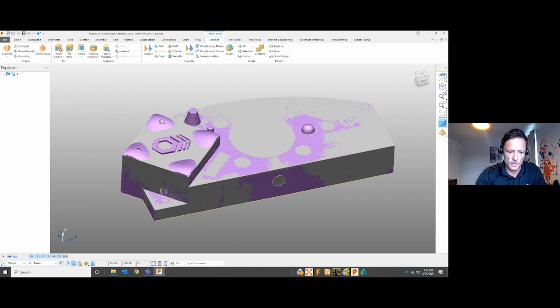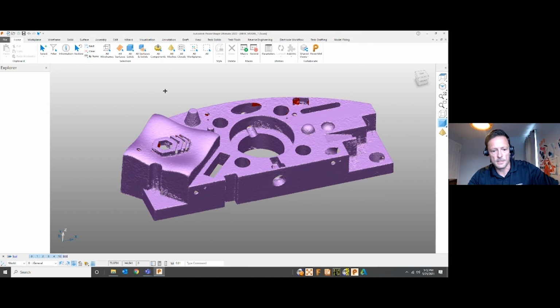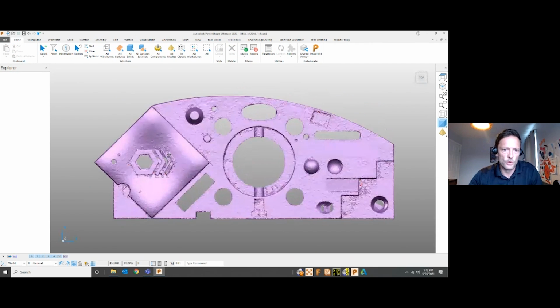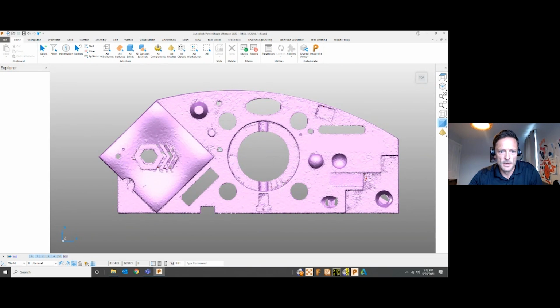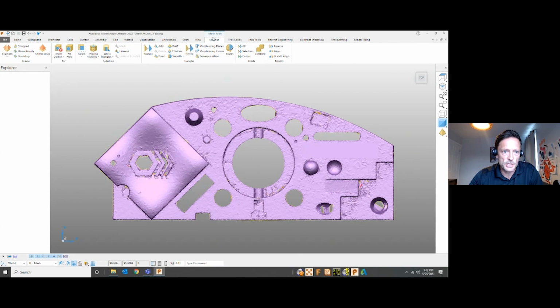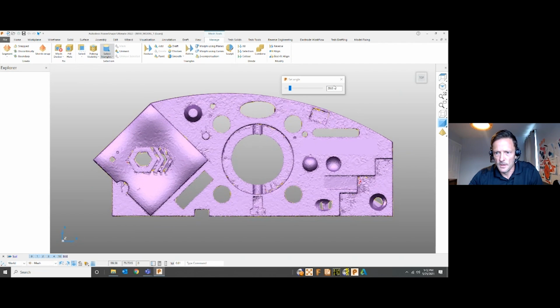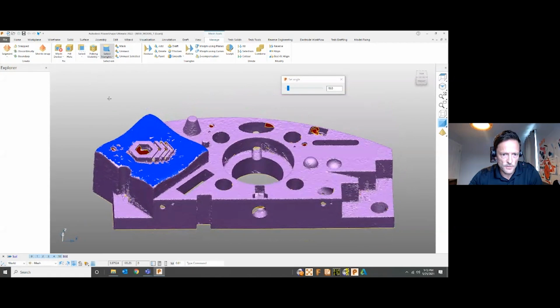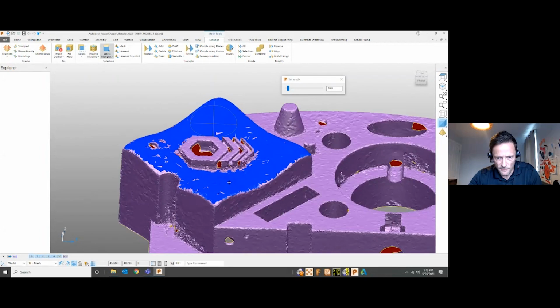So let's just grab that triangle mesh. We'll hit Control K to look at that on its own. And then we'll do something slightly different in this area. So if I click on the mesh, I go to the Manage tab. What we're going to do is select some triangles in a completely different manner, in this case by discontinuity. I'm just going to drop that down to about 10, click on the triangles, and again I'm looking for nice coverage on this 3D form.